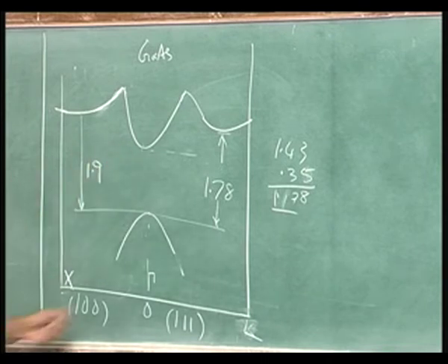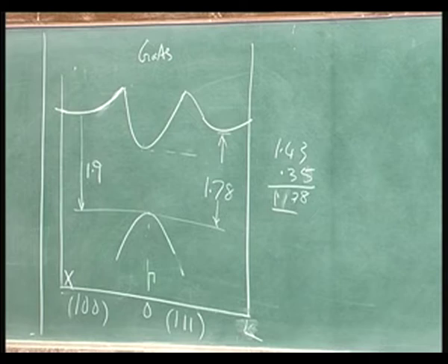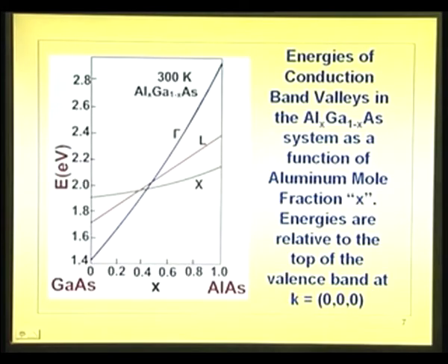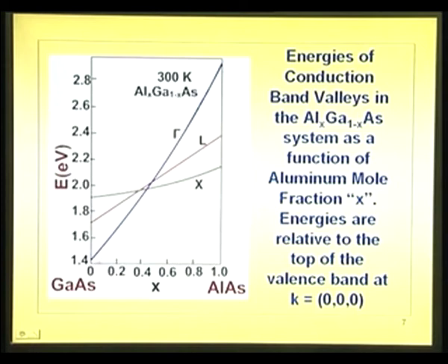In aluminum arsenide, corresponding to the center, that is an indirect band gap actually. Okay. So, you can see the tau, I will now come back to this. If you see here, this is the tau corresponding to the direct band gap, and there is a direct band gap corresponding to this level here, that one line going like that. It is not really straight, in fact, it will try to be straight, it latches on to the direct band gap, and if you vary x, that direct band gap keeps on varying from 1.43 to 3.02, that is what we have been telling. Earlier we were plotting this straight, strictly it is not so, it is not a perfect straight line, there is slight curvature here.